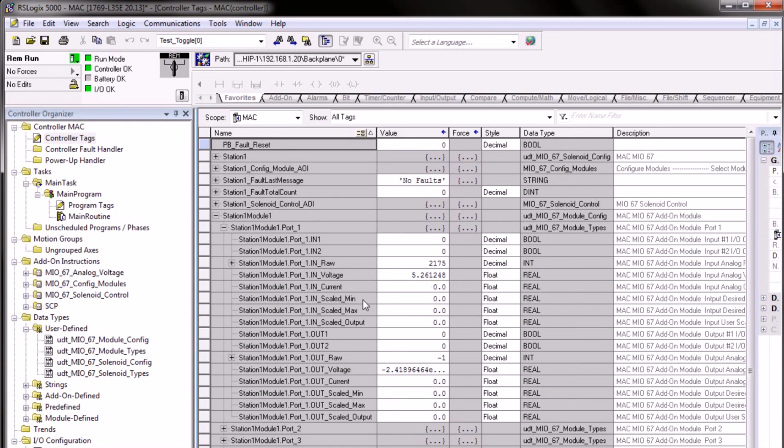One of the best features about the add-on instruction is a feature called Scaled with Parameters. This is this SCP block that is being used inside of the analog voltage module. These 3 tags are the ones that will probably be used in your particular output. The point of an analog module is to read the voltage that's incoming and scale it to an output value that means something to us.